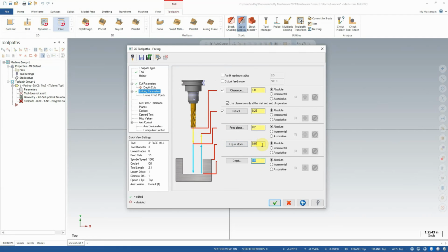So I would intentionally tell the operator, or I myself would know, if I was machining this part, that all of the tools will be touched off the Z0 position, and that only the first toolpath, the facing toolpath, and therefore the facing tool, is the only tool that would be touched off the rough surface at 50 thou above the part. So I would touch off, make my cut, and all my other tools would be set on that newly cut face. This would ensure accuracy of following cuts, as well as consistency throughout my program.